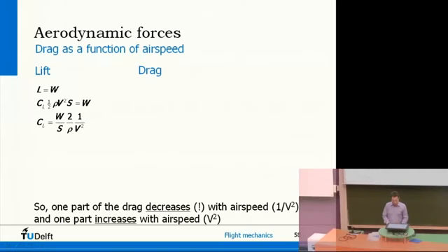But now let's have a look at the drag. We've just gotten this relationship, the aerodynamic lift-drag polar, which says there are two portions to the drag: the zero-lift drag coefficient, and the induced drag. Just to remind you, this term, and pi, A, and e, are all constants for a given aircraft.